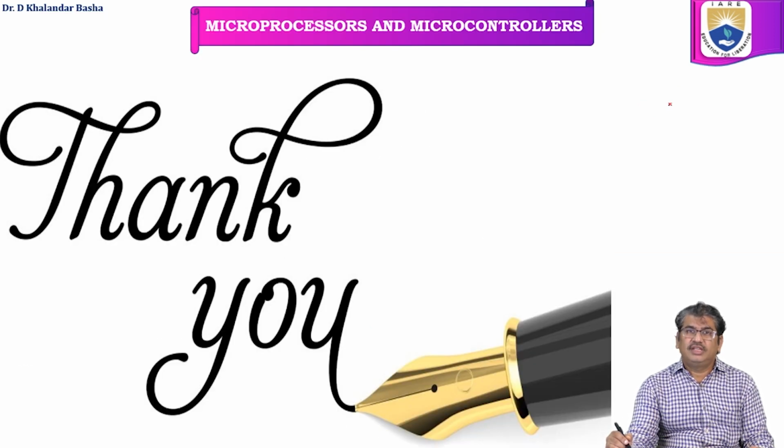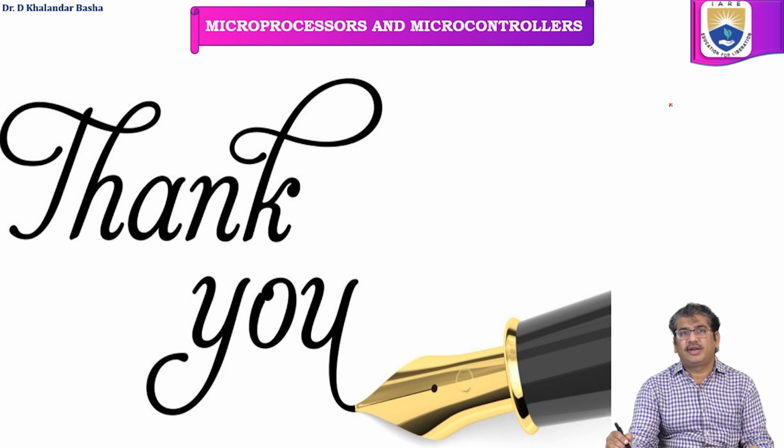Thank you all. In this session, we have discussed how to operate the 8086 processor in minimum mode and maximum mode. The various blocks required for minimum mode and maximum mode were discussed. In minimum mode, we require a demultiplexer for generation of memory read and write signals, similarly for IO read and write signals, by using the 8086 signals M/IO bar, read bar and write bar. Apart from that, we require latches for separating the AD address lines and data information on the basis of the ALE signal. The ALE signal will be 1 during T1 clock pulses. From T2 to T4, the ALE signal will be 0.